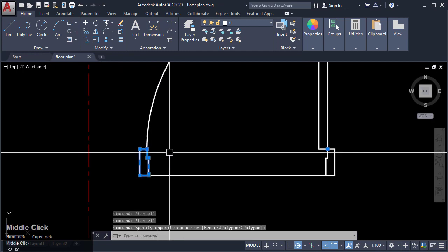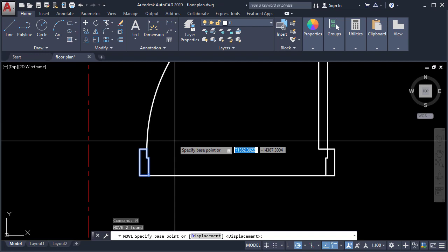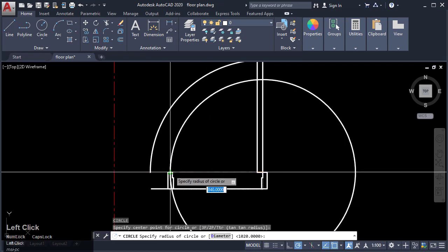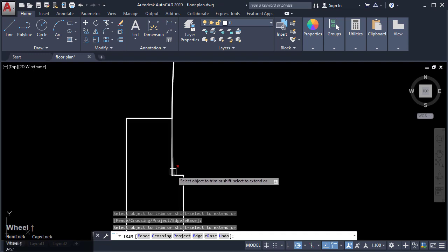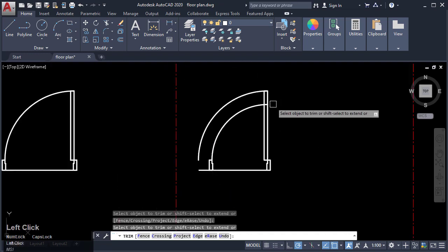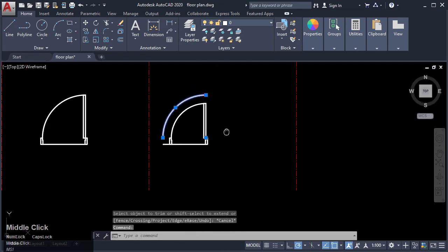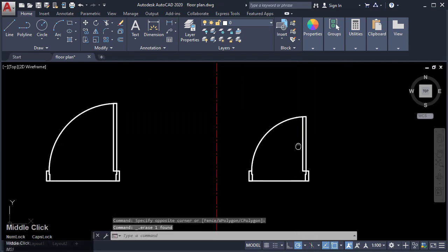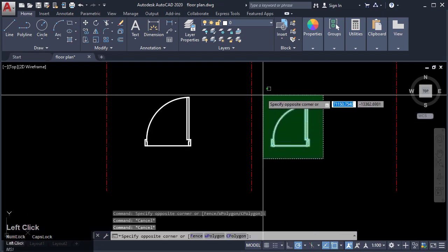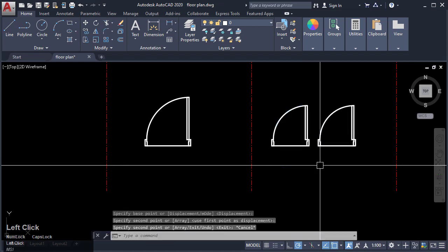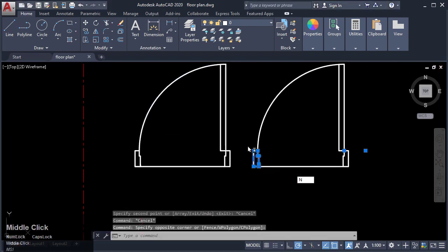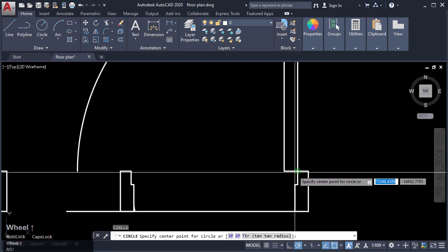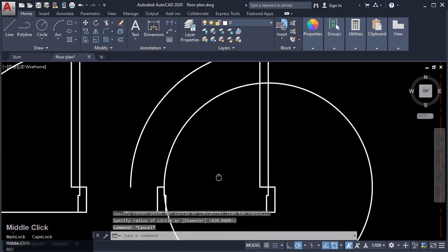So for our bedroom door, let's use a door of 800. So I'm going to move my door jamb by 200. Create again a circle. Trim. Then you have now your door for your bedrooms. Another one for our toilet, whose width is 600. So moving again your door jamb by a distance of 200. Trim.